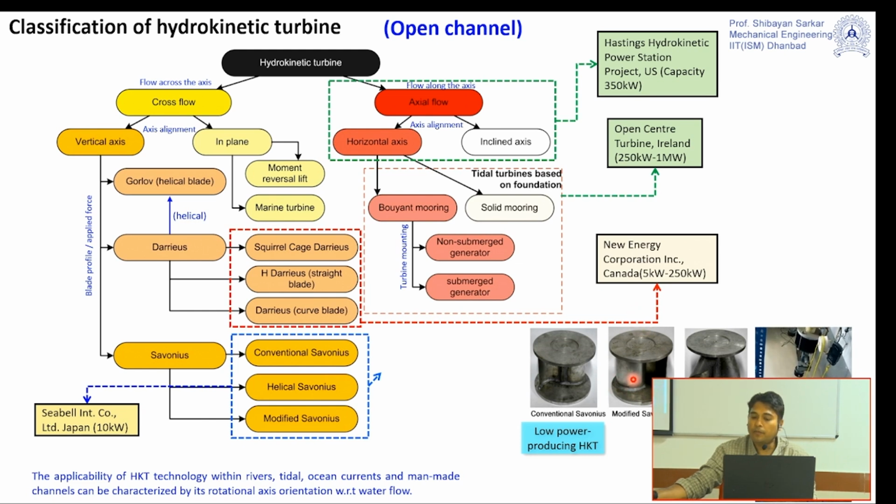So the top and bottom plates hold this blade and this blade, and there is a passage in between the two. So fluid can come, strike, glide over this particular blade, and then come out at the backside. That passage is intentionally created due to some hydrodynamic action. Those exercises are separate, but I would like to tell you that such different parameter changes are made in order to tackle different problems that generally arise when we design a particular turbine.